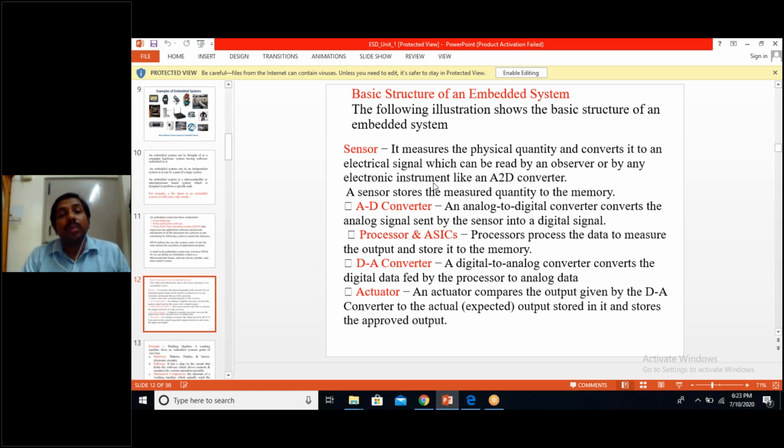For example, the room temperature sensed may be around 38 degrees, but you want to make the cooling to 25. So in the remote you set it as 25. Once you set 25 degrees Celsius, and the room temperature sensed is 38 degrees Celsius, based on the difference, the processor will generate the signals that are sent to an actuator.